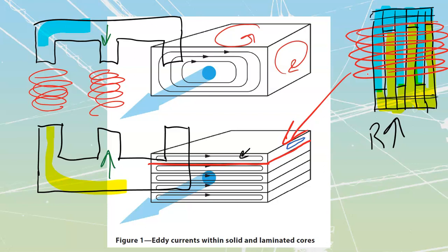As soon as that starts to happen, there will start to be insulation breakdown. So the varnish will break down over the years because it's ever so slowly releasing those VOCs. This is why transformers need to be taken in for periodic service, and electric motors as well. The rewinding and revarnishing is there just to put a new coating over top of that.